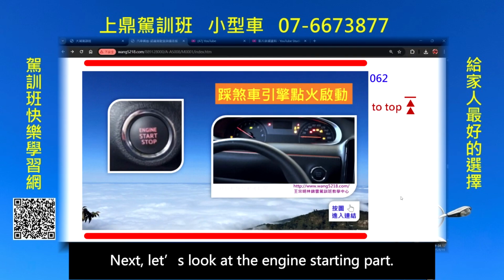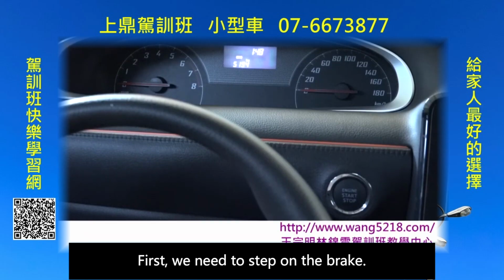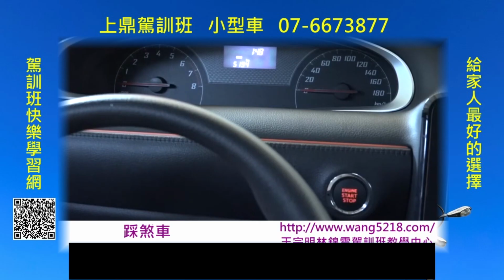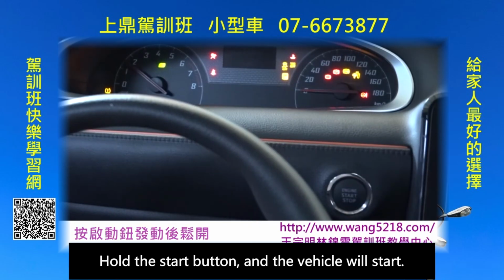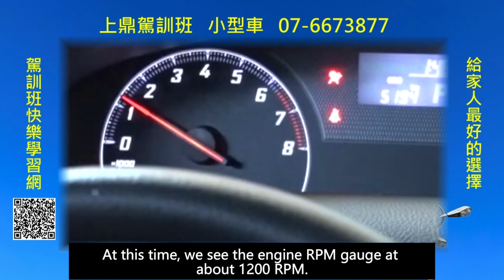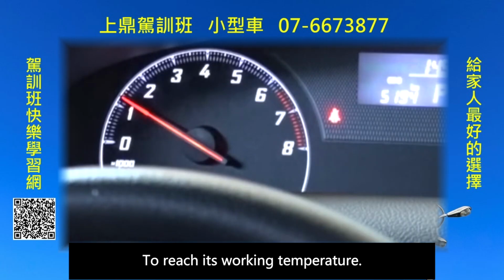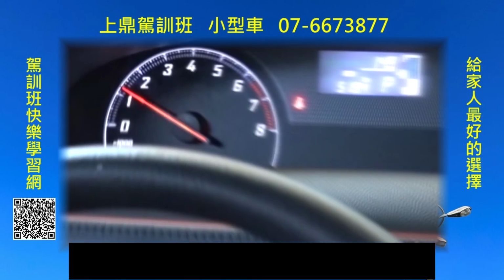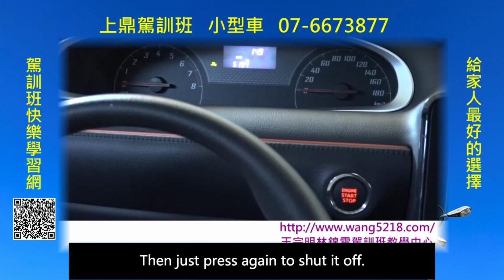Next, let's look at the engine starting part. First, we need to step on the brake. Hold the start button, and the vehicle will start. At this time, we see the engine RPM gauge at about 1200 RPM. Because during startup, it naturally raises its RPM to reach its working temperature. Next, when we turn it off, we do the same. Step on the brake, then just press again to shut it off.